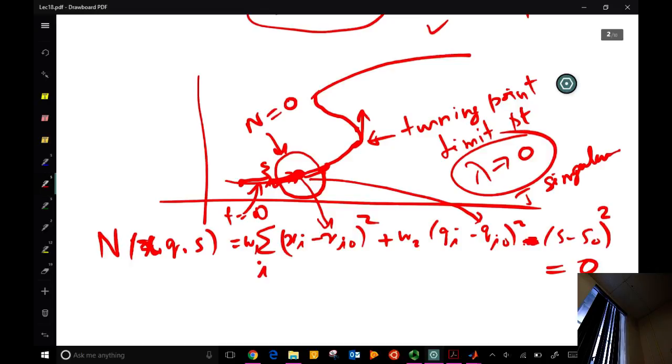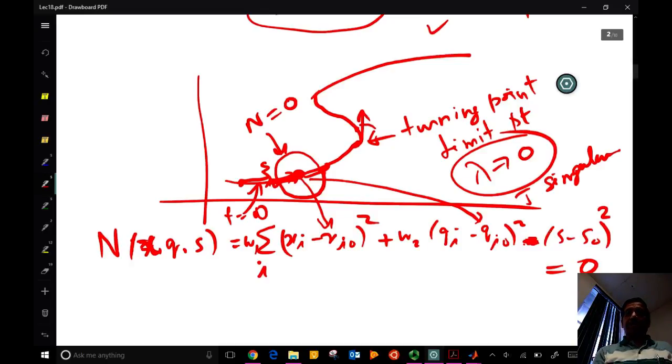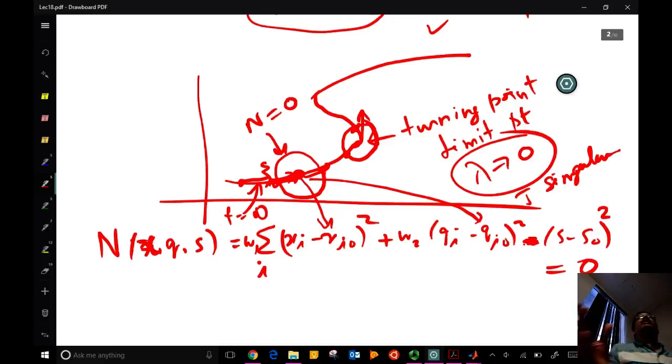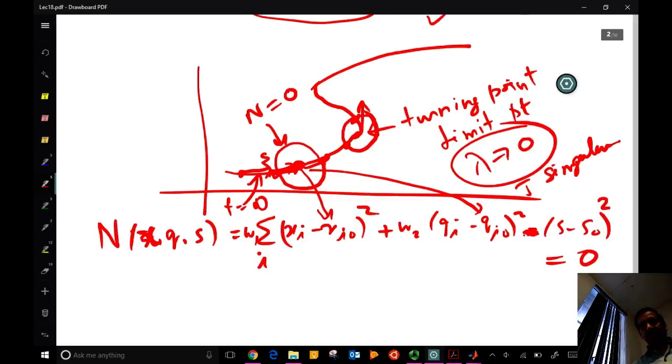That means I have a bigger circle, and I can find those solutions, right? I can make delta S smaller. I can change that variable. That becomes my control variable. Q is no longer the control variable, but S, the radius of that hypersphere, is. What is the beauty of this? If I take a point near this and I draw a circle, I will always have 2 solutions. So I've removed the singularity. But the challenge is I have an enlarged system of equations.